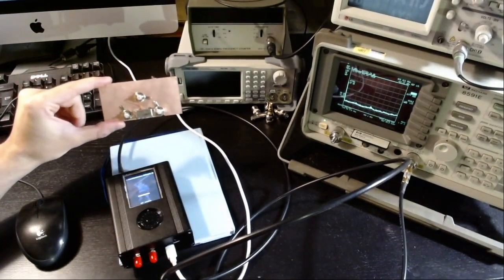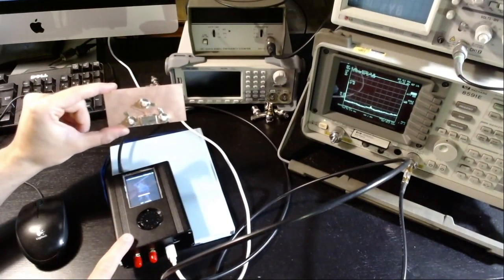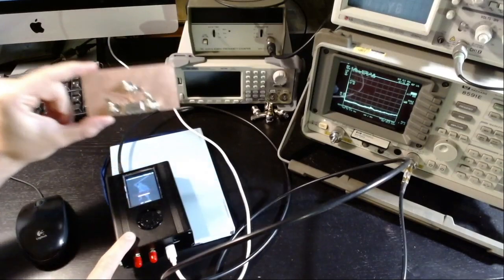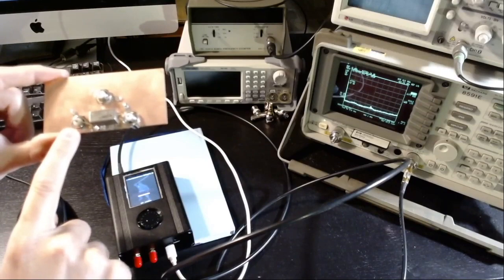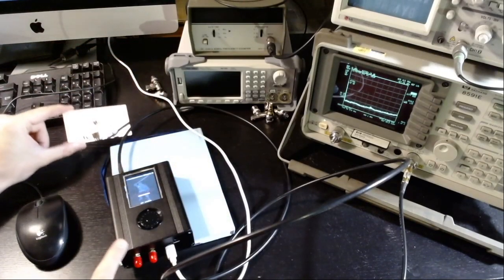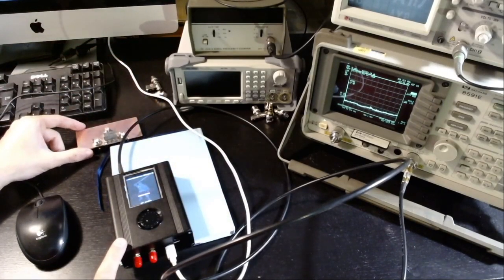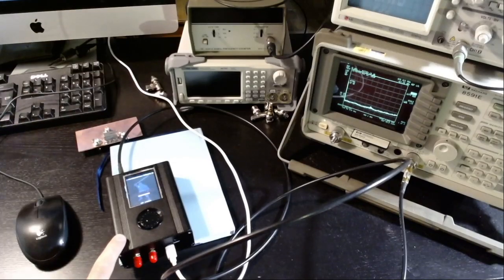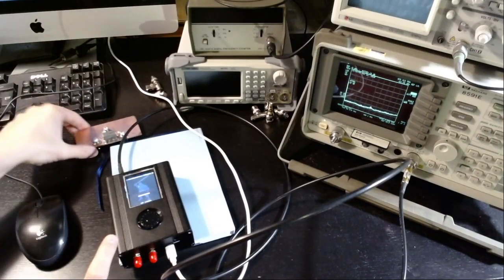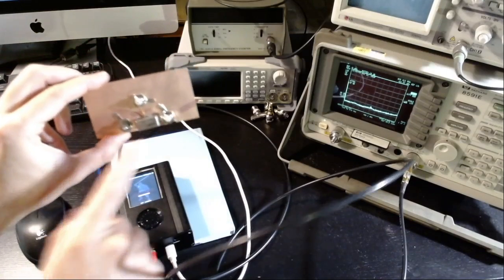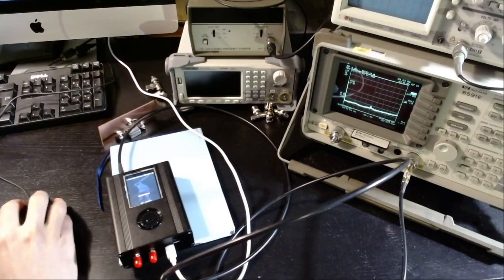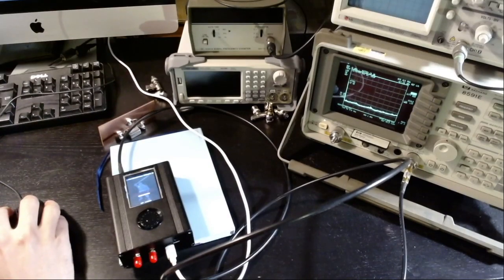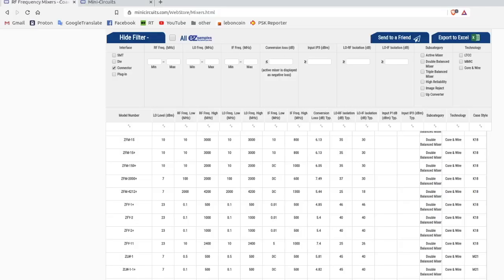And in my previous episode, number 28, I used the HackRF to drive the local oscillator port of the mixer. The great thing about the HackRF is that it can generate signals from 1 to 6 gigahertz. So in theory, I can drive the mixer with a local oscillator up to 6 gigahertz. Now this specific mixer that I've been using is not good for 6 gigahertz. It only works up to 500 megahertz.